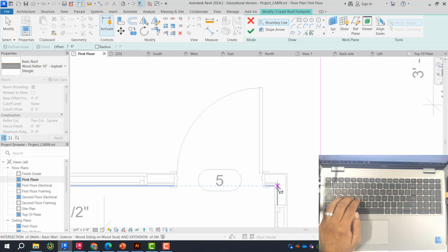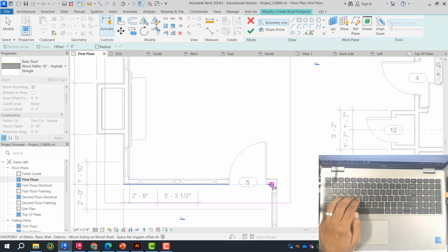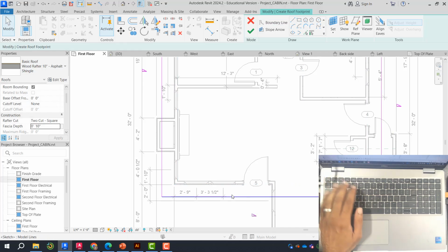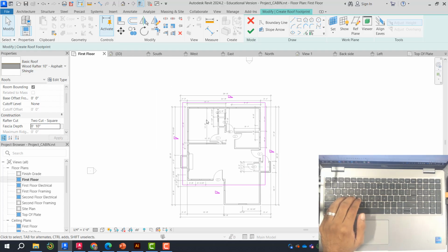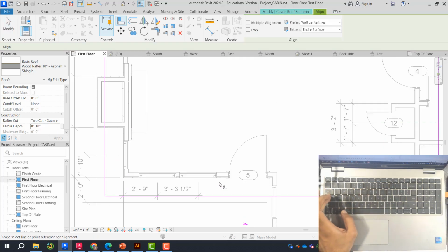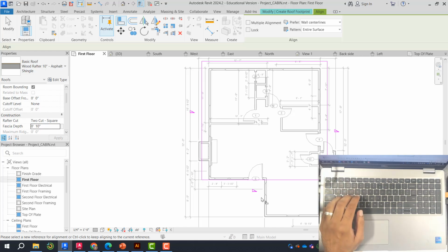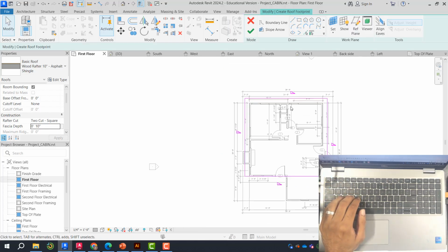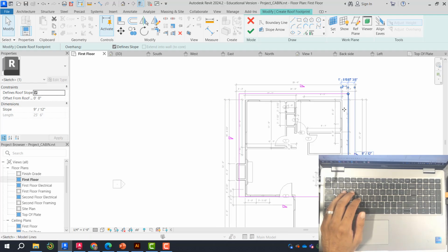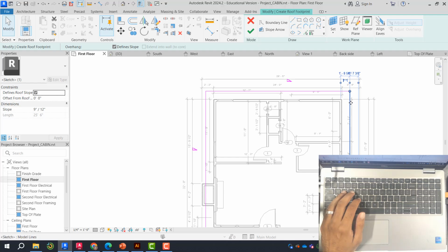I'm going to be aligning the roof to this face of the wall. I'm just using that as a reference because that's how the roof is drawn in the first place. And then I can simply come back in here. It's 1 foot 6 all the way around. I'm going to use the align command, AL, Tab, to cycle through my selection, edge exterior of that wall to here. So now I'm sloping up from here and going down to there. And now I'm going to simply select the edge face of this roof, which is already offset out 1 foot 6 inches from this wall.